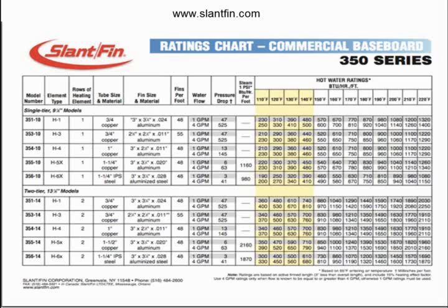Now the other thing that they've done, which was nice, is over the years they used to show these output charts for their fin tube, and I think they used to start at either 140 or 150 degrees. Well, they've gone back and they've recalculated those, and now they're taking these output charts all the way down to 110 degrees, which is wise because, again, they realize that the solar market and this geo market, these guys are going to be looking for outputs at much lower temperatures than what they used to publish there.